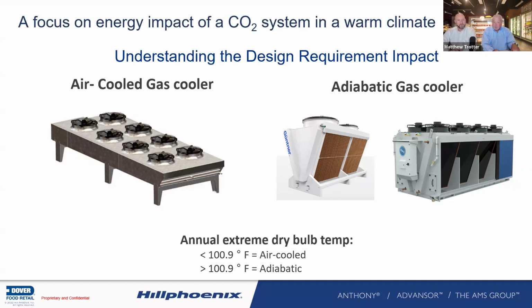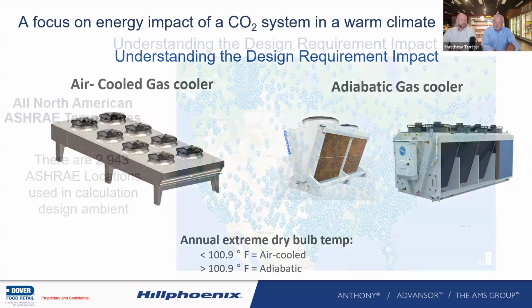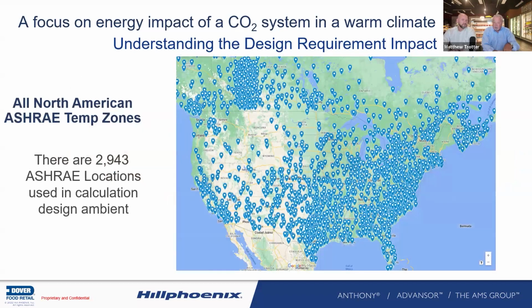In a warmer climate, air-cooled will still work. Most of the time it'll be subcritical, but we'll have to have some difference in energy usage when we're in that supercritical state that we talked about, which is why we often look at 101 degrees or above, we look at adiabatic. And what adiabatic will do is allow us to operate in warmer climates.